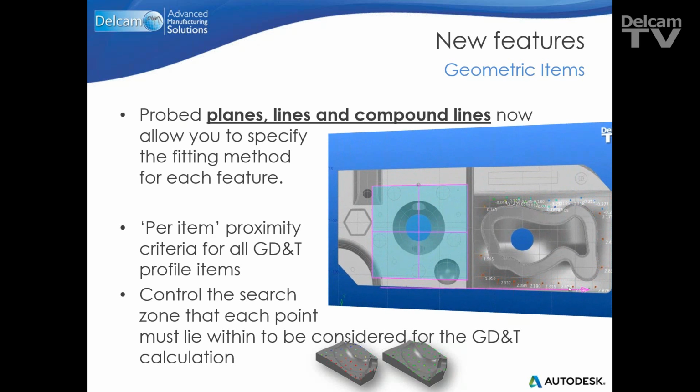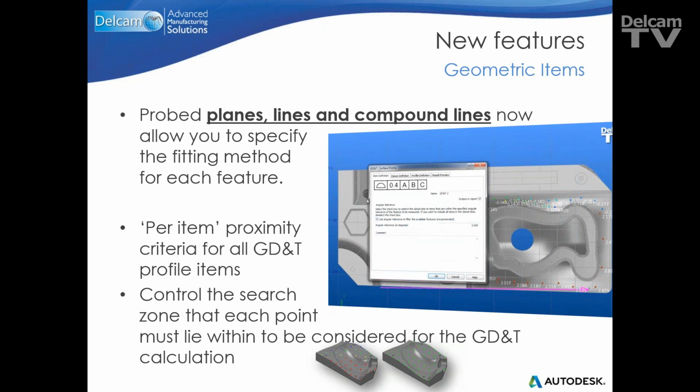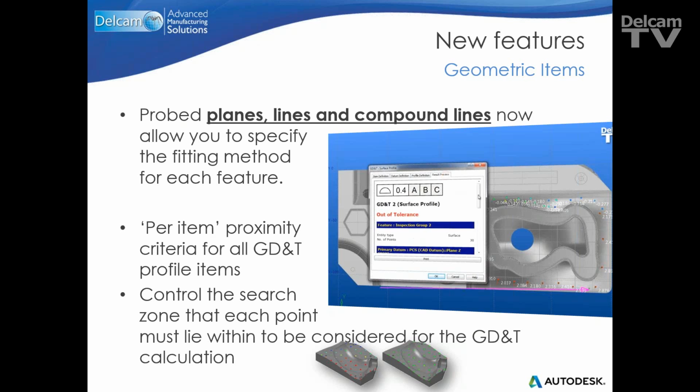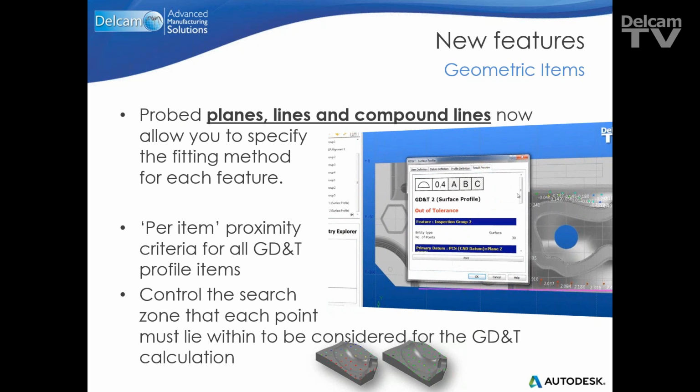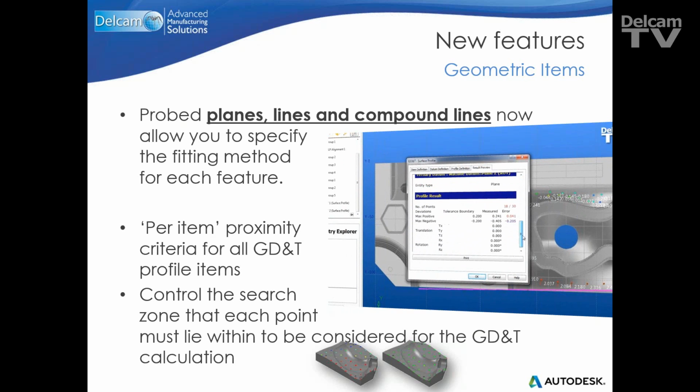So if certain points were higher and certain points were lower, perhaps for example a point in the middle might be slightly higher than a point on the outside, then we'd try and fit that, but it wouldn't quite work. In reality, when you're fitting something on top of something else, you need to use the maximum material condition. And we now allow that fitting method in PowerINSPECT. The maximum material condition is represented by the 3 highest points.